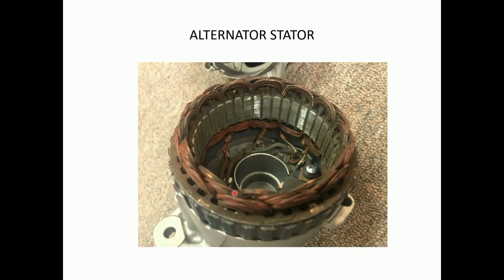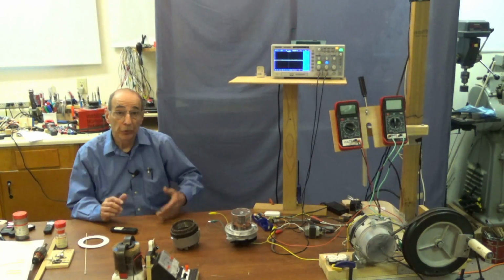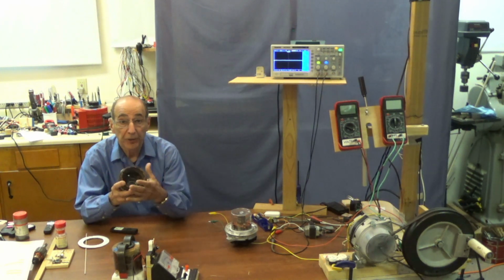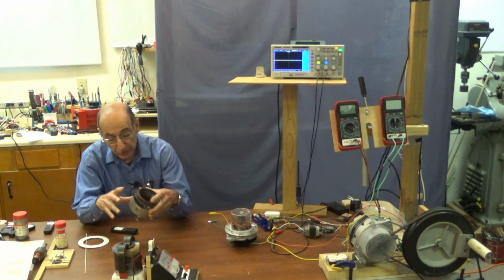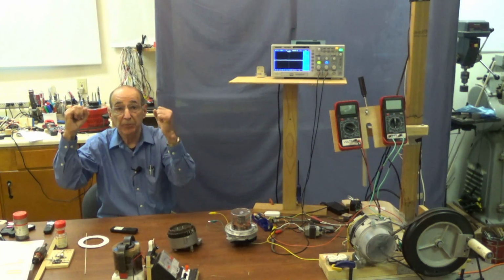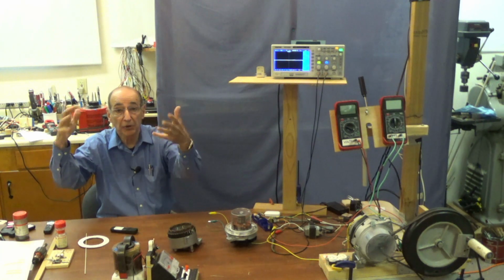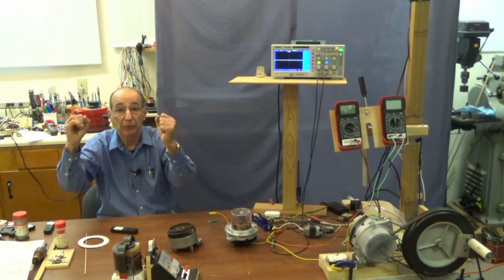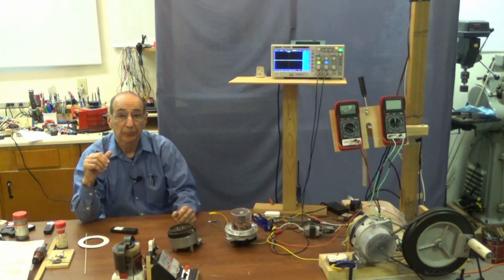Each one of those, all the 1s produce a sine wave, all the 2s produce a sine wave, all the 3s produce a sine wave, and they're out of phase with each other, kind of equally spaced. The reason we use 3-phase power is because we can produce a more compact alternator, and also we can transmit more electricity over the same amount of conductor, whether it's aluminum or copper. We can send more electricity over the same amount of metal as efficiently.